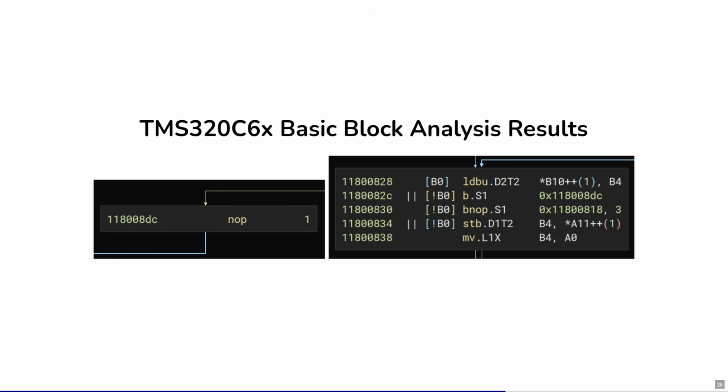But the reason we see on the right part, this is part of a larger loop, and we are queuing multiple branches. With the same condition, you see it's not B0, and there's B for branch and BNOP for branch and wait, and then we have multiple targets. And this means that we first branch to this block with the nop, and then branch away again.